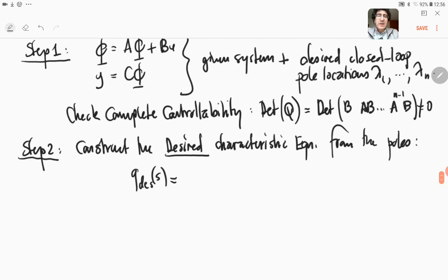In fact, we will not need the full transfer function, because the controllable canonical form only uses the part that we are interested in: the B and A matrices use only the denominator coefficients.